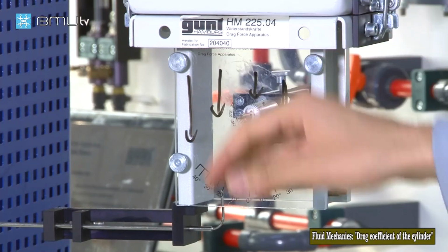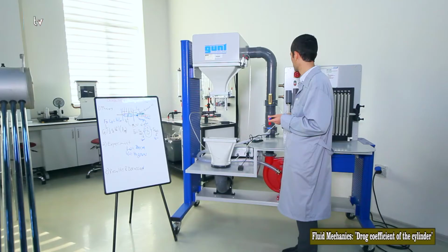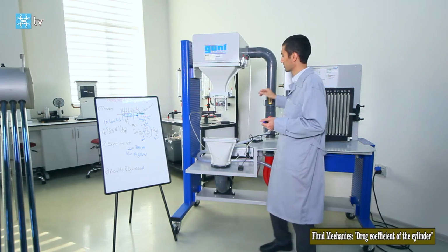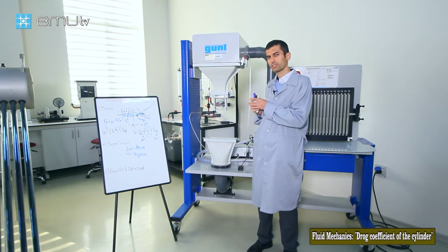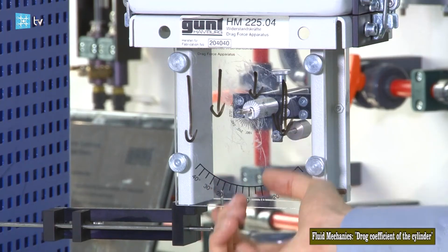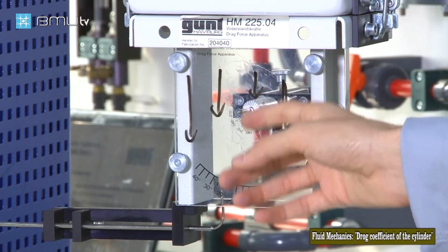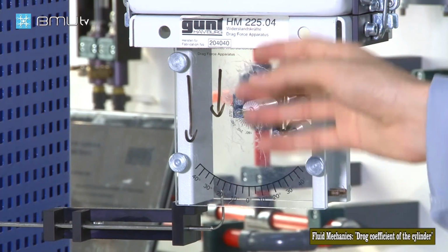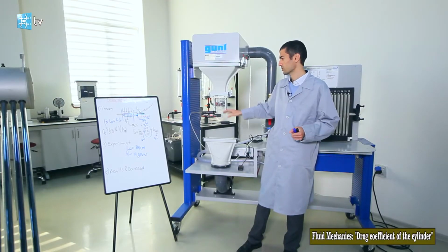Okay. But the body moves up and down because it is due to vortices. You can see it oscillated, but it is due to vortices, also called the von Karman street, that is created behind the body. That shedding of vortices has some frequency. That frequency creates a periodic force acting on the body, and that harmonic periodic force oscillates the body up and down. It is not so important for our case because at the end it was in equilibrium.